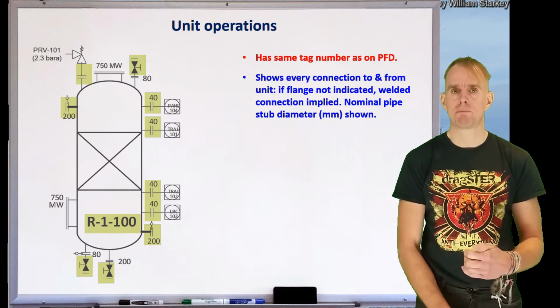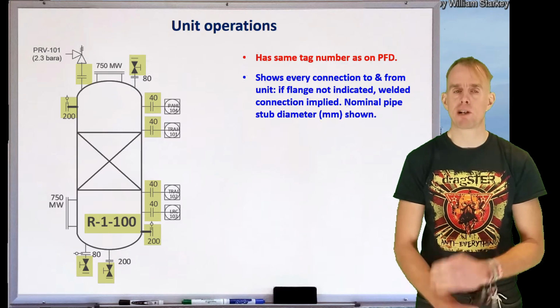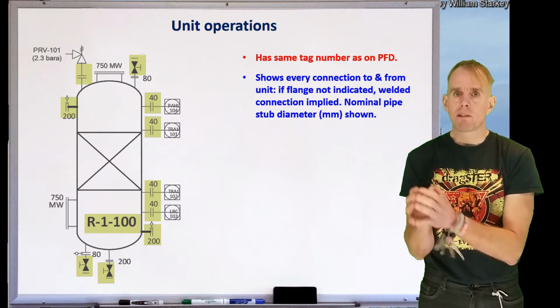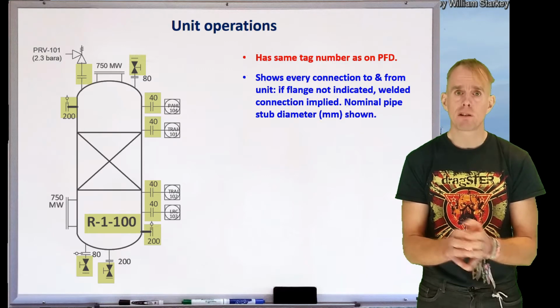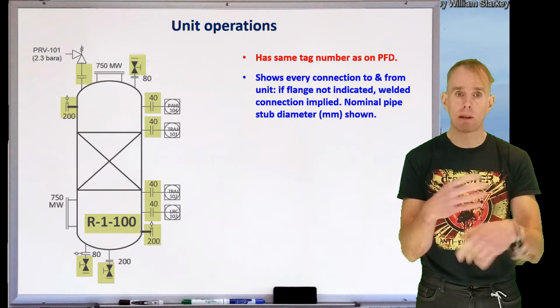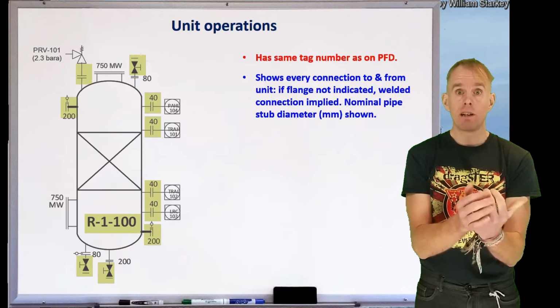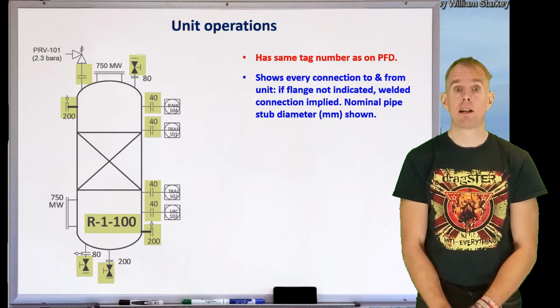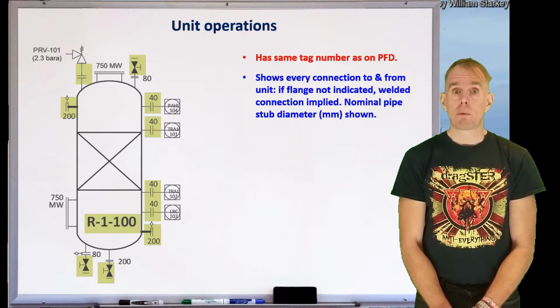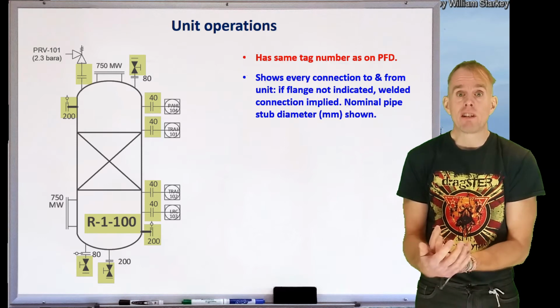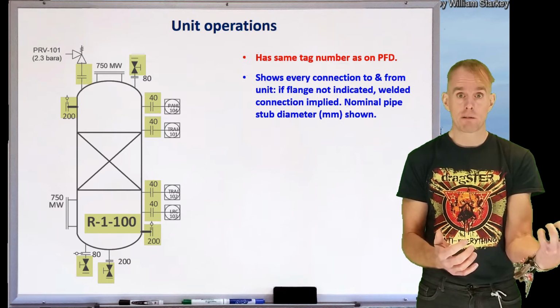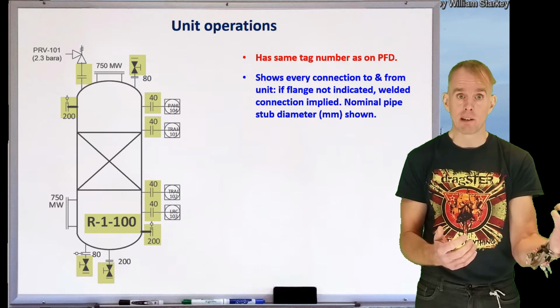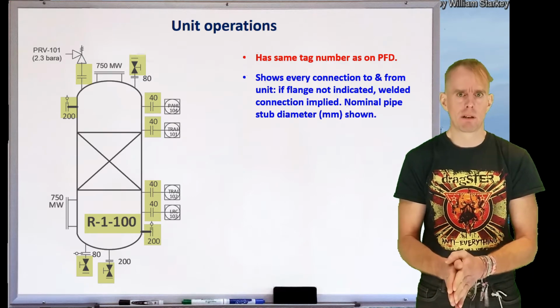If we've got pressure measurement devices or temperature measurement devices, these instruments actually need to make physical contact with the fluid inside the vessel. And so a pressure measuring device typically will have some sort of strain gauge element that needs to be exposed to whatever gas is inside the vessel. Likewise, a temperature measuring device needs to actually stick into the vessel somehow, such that you've got an accurate measurement of what's inside the vessel, not what's happening inside the vessel wall.